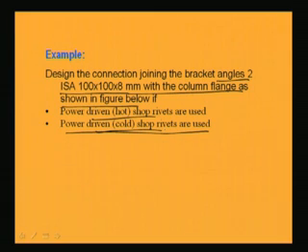So, we will see how the calculation is going to vary and how to design for the hot rivet and for the cold rivet. Hot rivet means the neutral axis is at the mid of the connection, at the CG, and cold rivet means neutral axis will be at h by 7, if h is the total depth, then h by 7. So, in this way we have to do. So, let us see the connection.